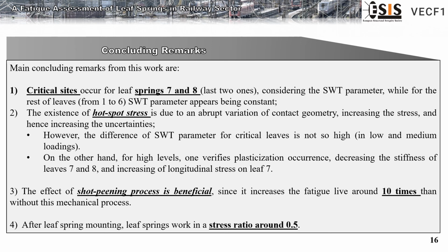The shot peening process is beneficial since it increases the fatigue life around 10 times compared to without this mechanical process. And after leaf spring mounting, leaf springs work at a stress ratio around 0.5.